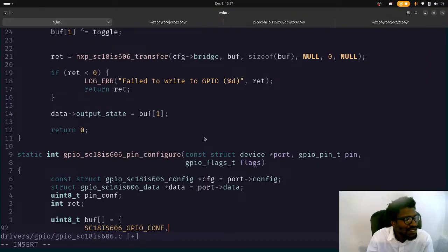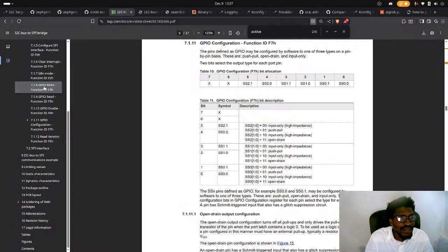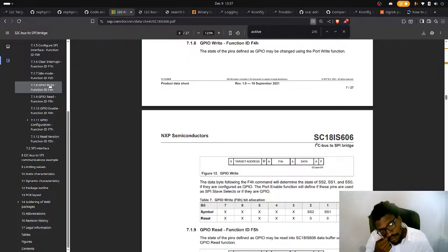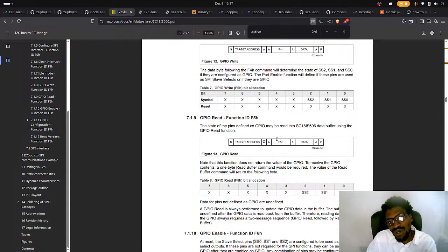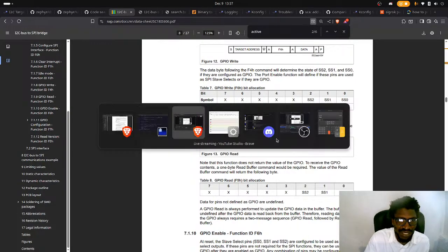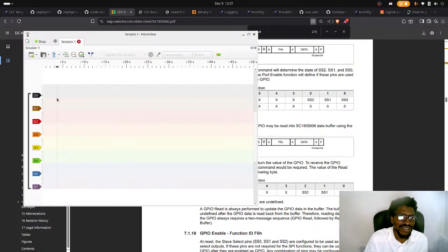But even if it's a mask, it's not actually doing the right thing, because it's right, F4H, yes. Enable F6H, yeah, those seem to be doing just fine. There's some toggling that we're missing somewhere between our driver and the actual device, because this shouldn't be this way. If I run it, this should not be high all the time. D1 should not be high.